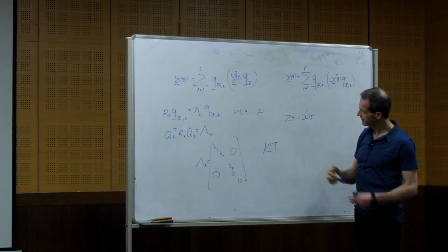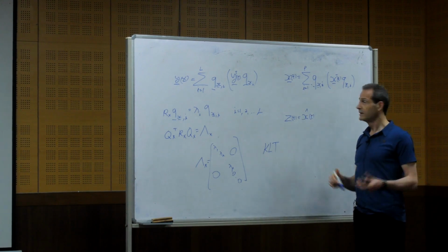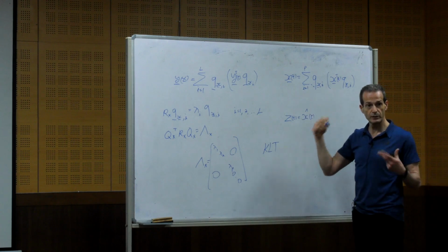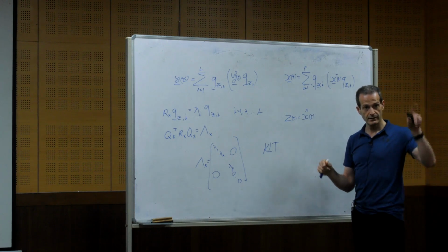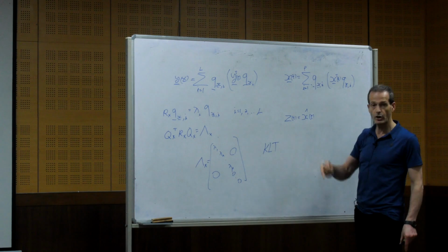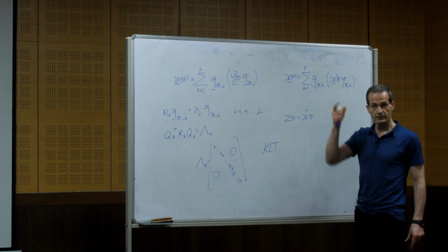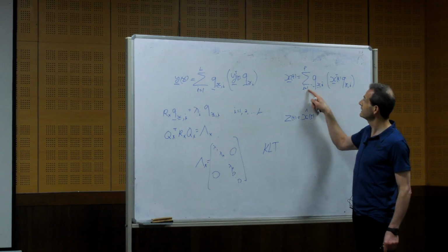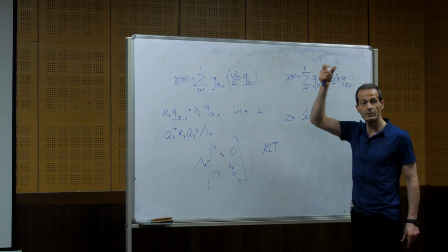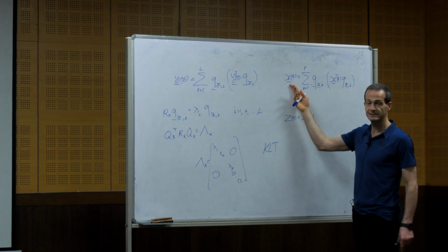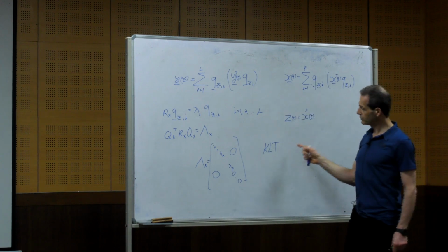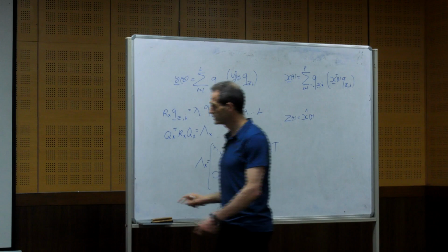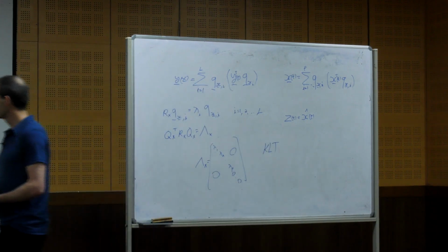So if we take the Fourier transform matrix, L by L, and we take its columns, maybe we need all the vectors to represent a signal X. That's why we move to the Karhunen-Loeve, because here it depends on the rank.